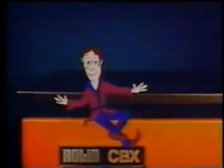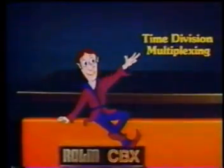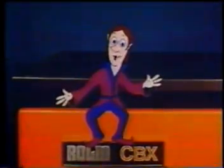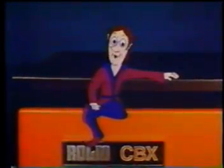Today we're going to look at two of the most important design principles used in the ROLM CBX, time division multiplexing and pulse code modulation. In the past, you had to dedicate one wire circuit for every discrete voice signal. However, with the application of time division multiplexing, or TDM, the ROLM system allows multiple voice signals to travel along a single digital bus. And how is this accomplished, you may ask? Well, basically by the use of a digital computer and the high-speed division of time.